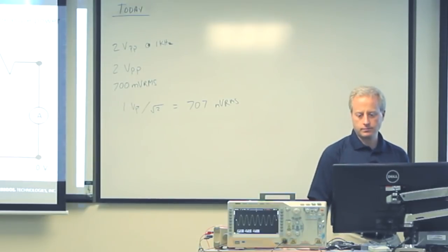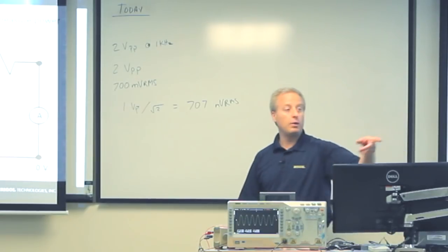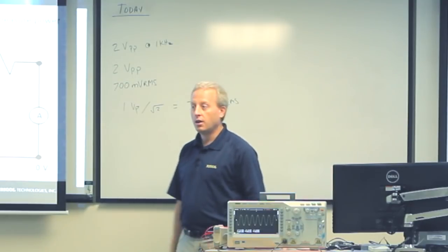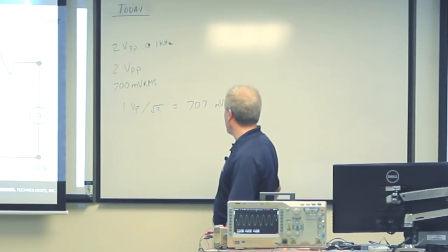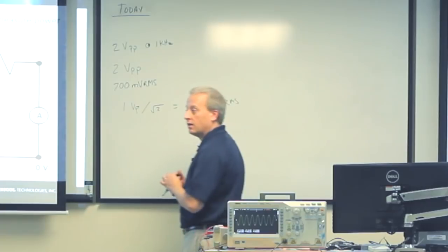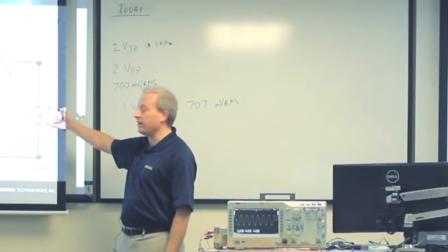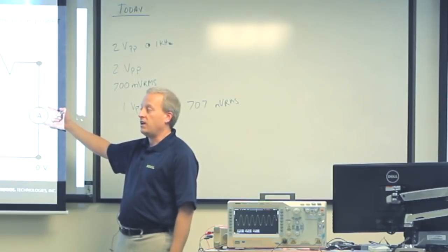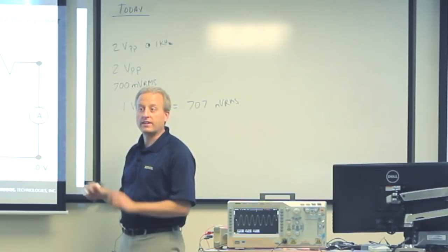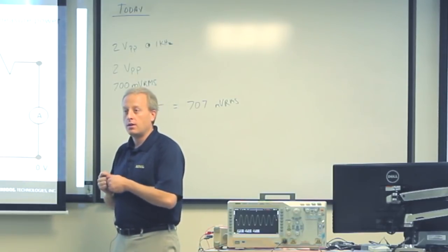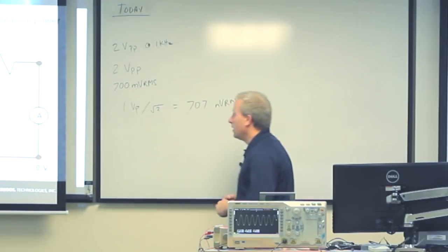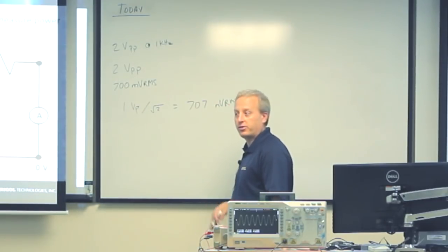All right. And then I think we had at least one person who was set up nicely to measure the AC current RMS as well, right? So if you put the ammeter here like we had before and put it into AC current mode, you'll get the current in RMS. And again, the purpose there is, we want to know how much power this resistor is taking, right?